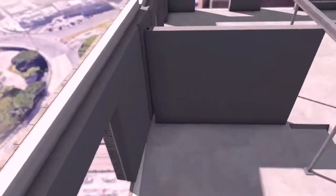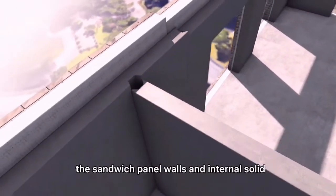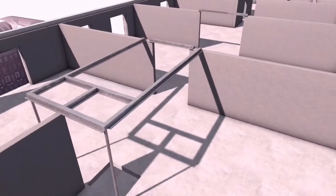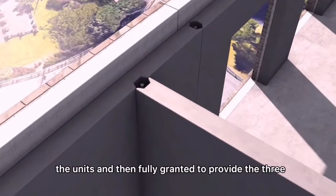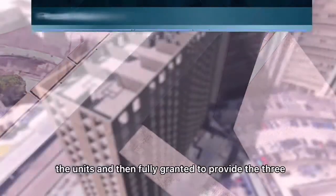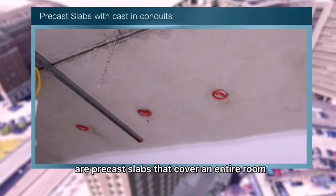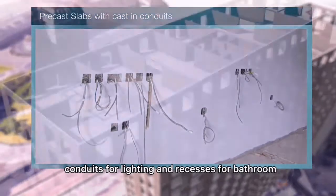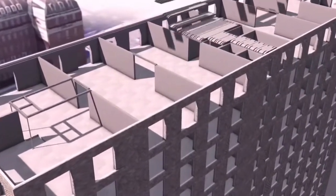Installation is clever but simple, satisfying the approved document of the building regulations. Sandwich panel walls and internal solid walls have continuous vertical ties, and floors are horizontally tied to their support, and the unit is then fully grounded to provide a 3D type structure. Placed on top are precast slabs that cover an entire room. They can have cast-in conduit for lighting and recesses for bathroom pods.